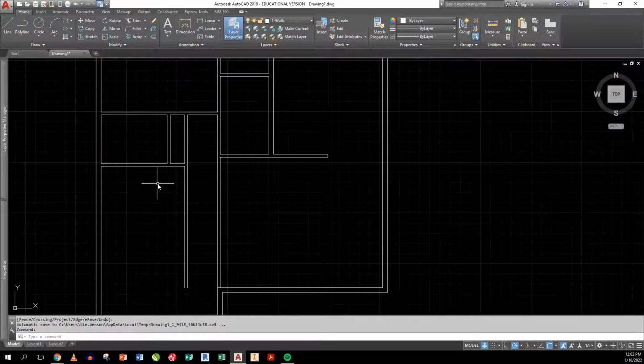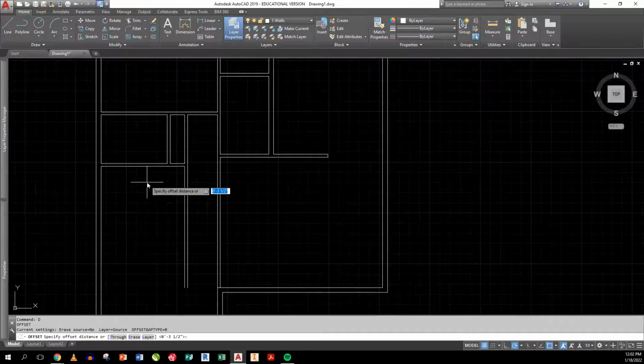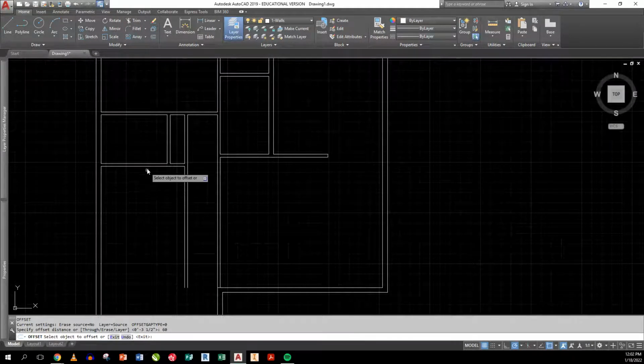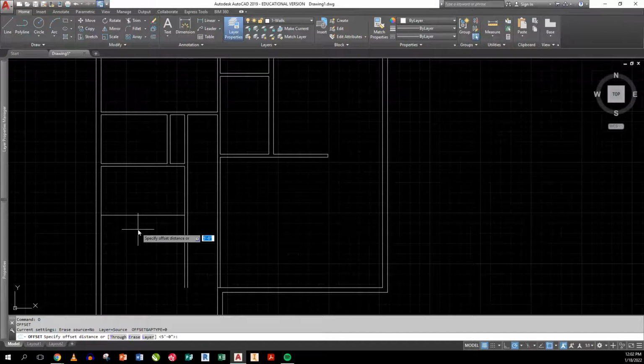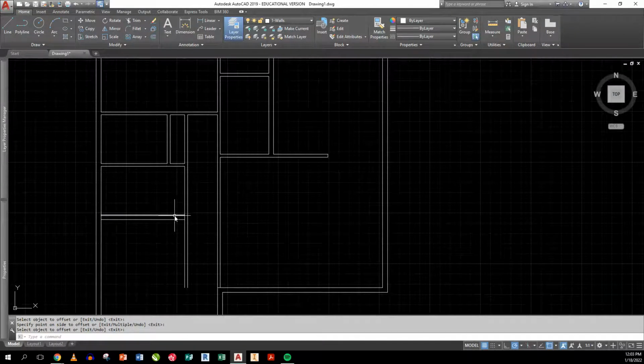Now the bathroom is exactly 5 feet across from inside edge to inside edge. So offset 50 inches or 5 feet, same thing. Okay. This time I need to put a plumbing wall on this side. So I'm going to go offset 5.5 and put a plumbing wall in there. Now the reason this wall is called a plumbing wall and so is this one is because we have to put the plumbing inside that wall. Otherwise it will not work, because the plumbing, like soil stacks, are nearly the same size as a 2x4, which is what a partition wall is made out of.